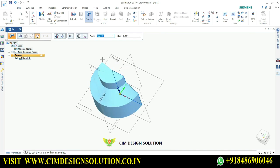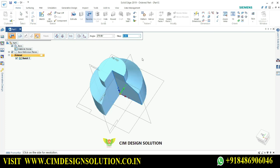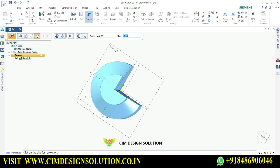Now I need to give angle, so whether it may be 360 degree. If I put 360 degree, you will get a complete cylindrical object. If you put here say 270 degree, you see one quadrant in many directions has been left.